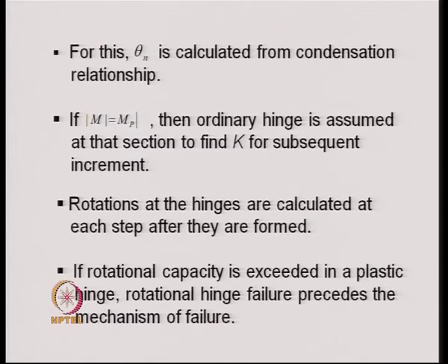Those incremental rotations are added to the previous rotation to find the current value of the rotations. Knowing the rotation and the story displacement, one can find the bending moment at the desired cross sections of the structure.